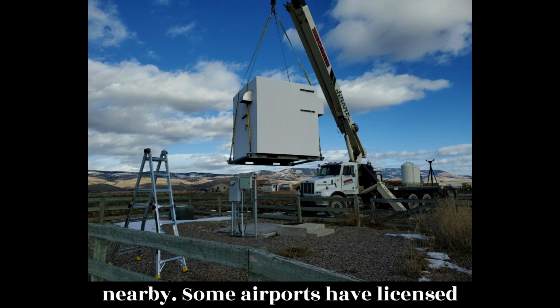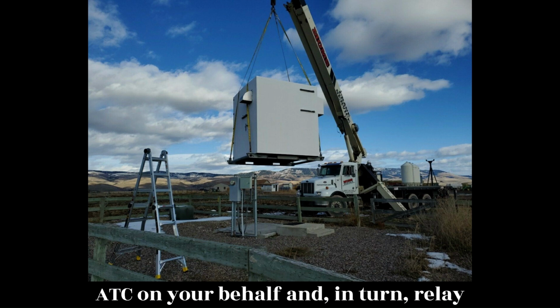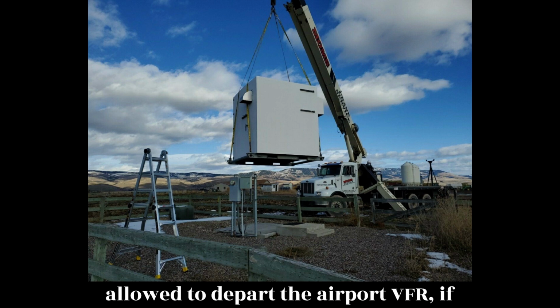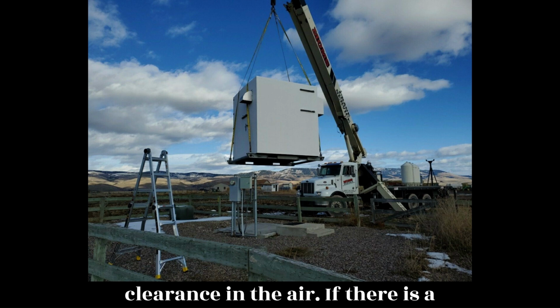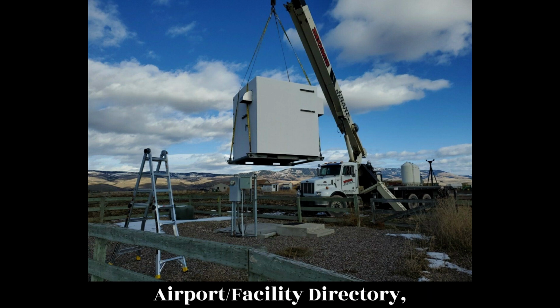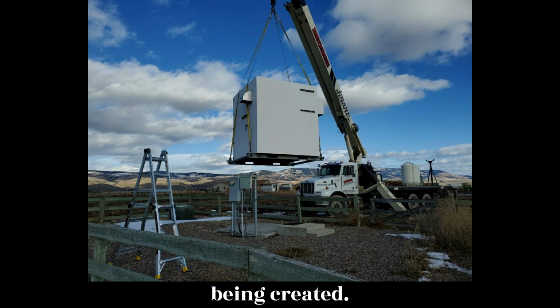Some airports have licensed Unicom operators that can also contact ATC on your behalf and, in turn, relay your clearance from ATC. You are also allowed to depart the airport VFR, if conditions permit, and contact the controlling authority to request your clearance in the air. If there is a direct line to the controlling ATC facility, the phone number is published in the Chart Supplement US, formerly Airport/Facility Directory, A/FD. As technology improves, new methods for delivery of clearances at non-towered airports are being created.